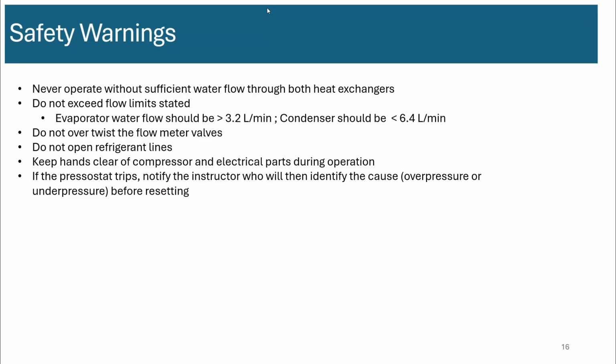Do not attempt to open any of the refrigerant lines. The compressor and the electrical parts of the compressor, mainly the capacitor, you should keep your hands clear of them to avoid the risk of potential electrical risk and also thermal risk. Compressor is typically more than 80 degrees C hot, so you could get minor burns if you touch it. Okay.